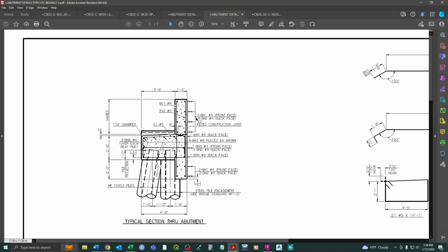So to get our total span length, we have 1 foot 3 inches plus the 1 foot 4 inches that we mentioned to get to the beam, then the total beam length, and then we essentially have those values on the other side. So this is on both sides. So you need to add 1 foot 3 inches times 2 plus 1 foot 4 inches times 2 to your span length. Okay, and then that'll get you your total length.